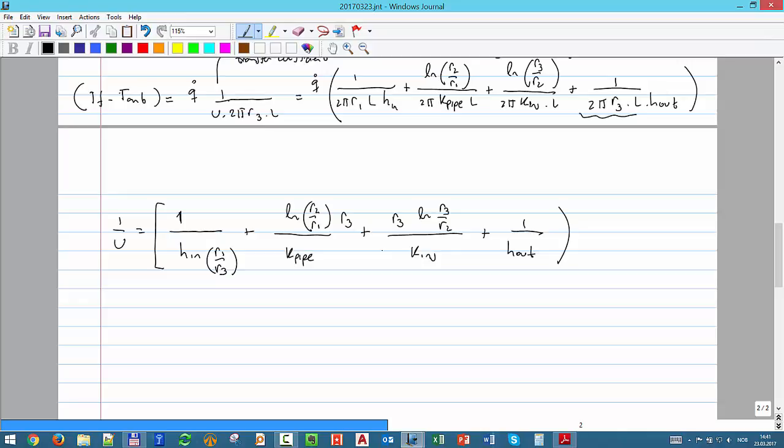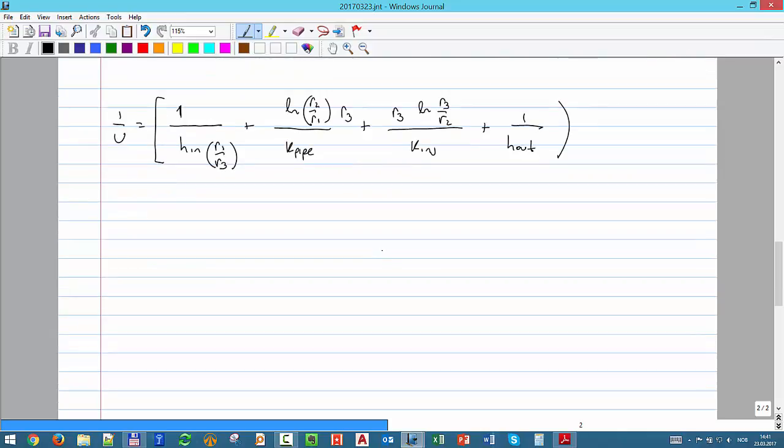Also, I told you that you can use the same idea for wells. You have an annular space with mud, and then you have cement, casing, many multiple layers. You can do the same approach. The only thing is that the expression will be bigger and bigger and bigger, but it's very practical. I think it's very powerful for heat transfer.